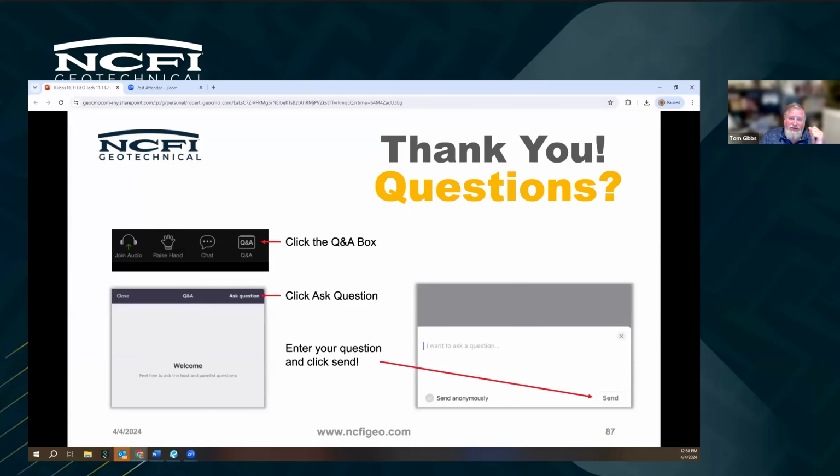Or there are some small versions of dynamic cone penetrometers that are reasonably priced. But DCP is not a bad way to test if you can avoid any lenses of foam. If you hit any of the lenses of foam, it's going to throw the test off. So with polyurethane, you have that possibility that the foam can lens off and follow that path of least resistance. So if you shoot on a 4-foot grid, it doesn't mean that you're going to be able to take a DCP right in the middle in between those and not end up hitting some foam.